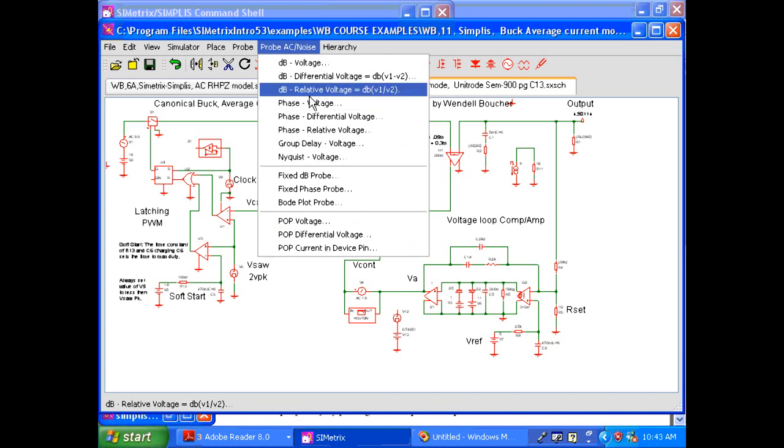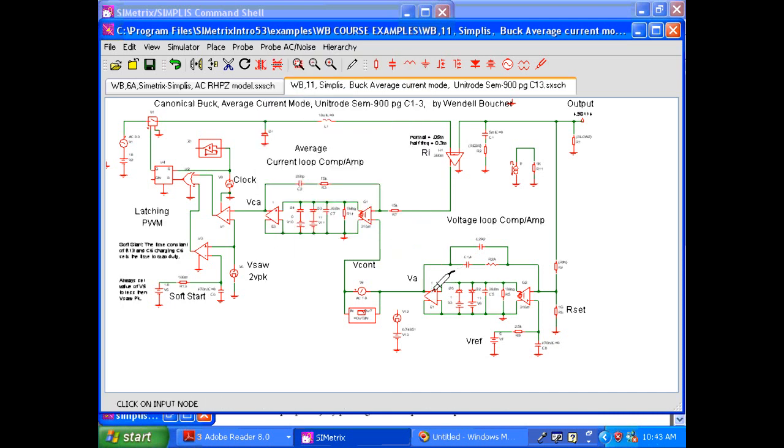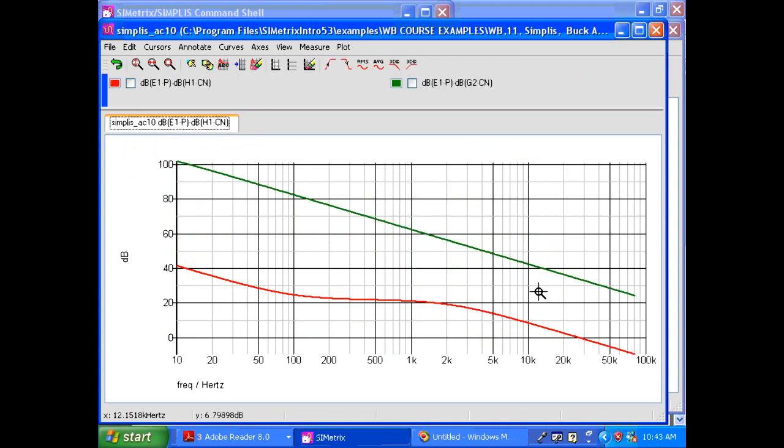It's also important to do this. Output of the amplifier to the input of the amplifier. Now we're looking at the open loop gain of the amplifier, and it's always necessary for this compensated curve to be well within this one, certainly within 5 dB. If it doesn't, what happens is the pole emerges. That's how we generally describe it. And if we say we had a -1 slope, it'll turn into a -2 if the internal pole emerges. I'll show you that whole amplifier curve. We'll shut this down.